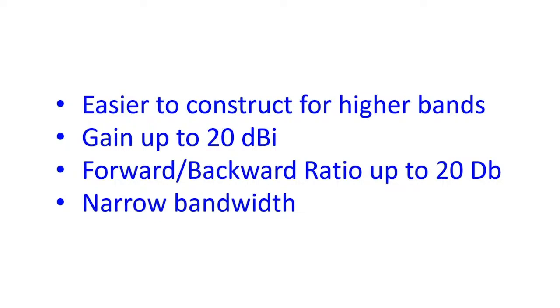Radiation pattern is linearly polarized with horizontal polarization for a horizontally mounted antenna and vertical polarization for a vertically mounted one. Bandwidth of Yagi-Uda antennas is relatively narrow, with a narrow range of frequencies within a band at which it has good gain and operable feed point impedance.